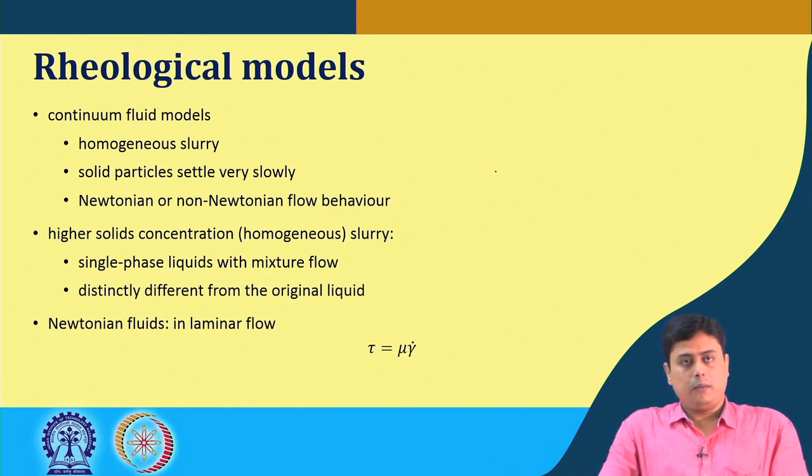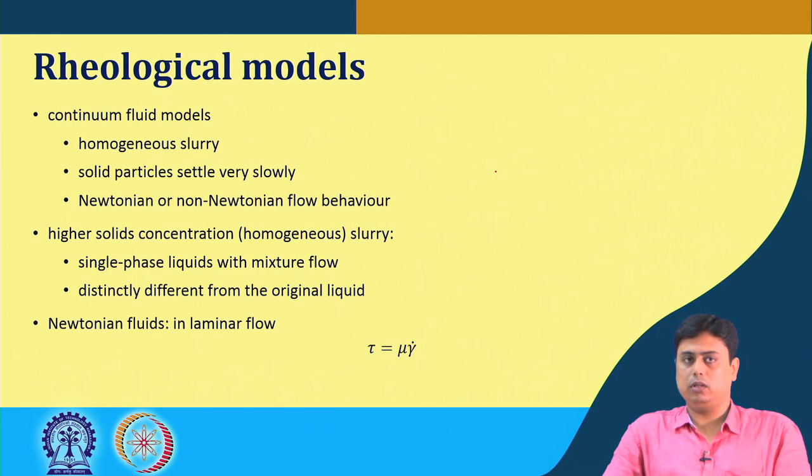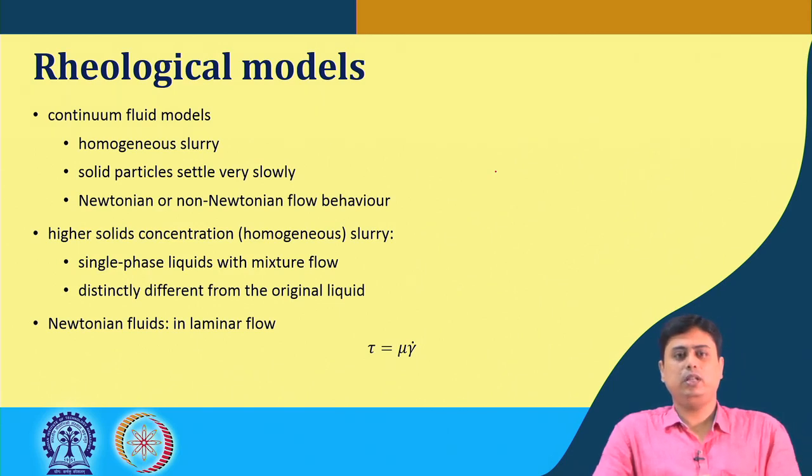Here, typically all the models for the rheology of slurry transport are based on continuum fluid models, and that is valid when the solid particle settles very slowly, or remains suspended till it reaches its destination or for a longer time.